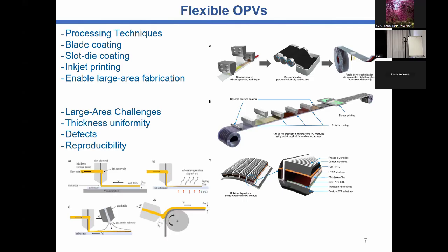And then in terms of roll-to-roll, these depositions are scalable because usually you are using substrates that are flexible, so they need to be rolled in the end. The meniscus is coated near one roll to increase the wettability and also the deposition.